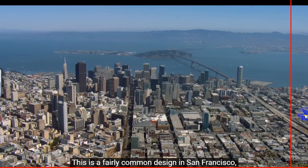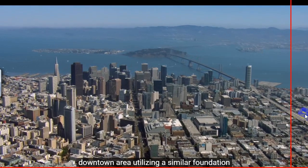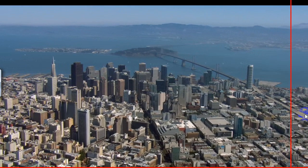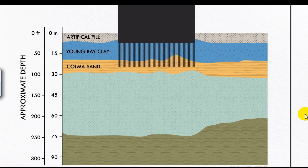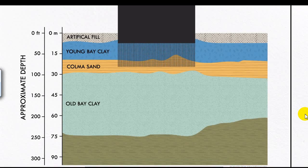This is a fairly common design in San Francisco, with more than a dozen tall buildings in the downtown area utilizing a similar foundation system, including some nearly as large as this one. However, it's not the dense sands causing problems for the Millennium Tower, but what's underneath. Below the Colma Formation is a thick layer of Ice Age mud, locally known as the Old Bay Clay. Thanks to the geologists for that name.